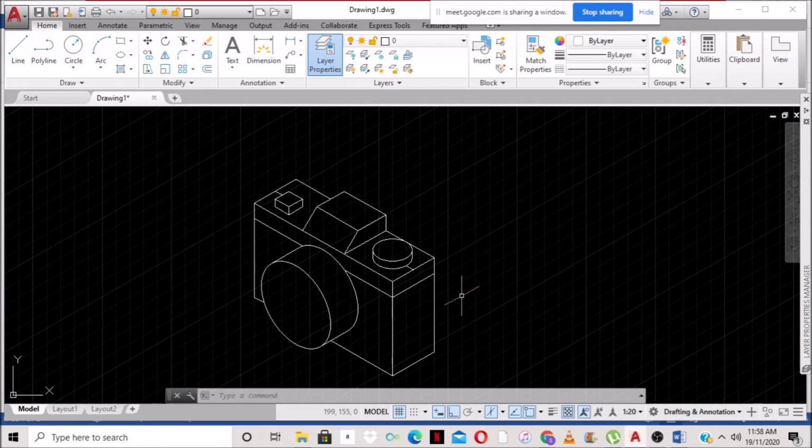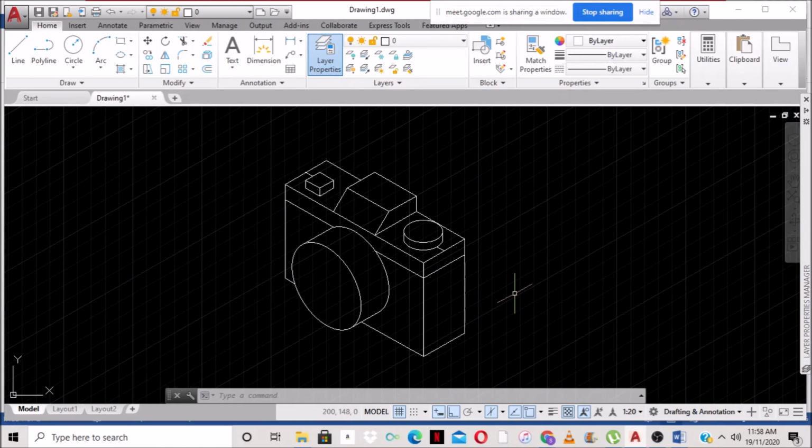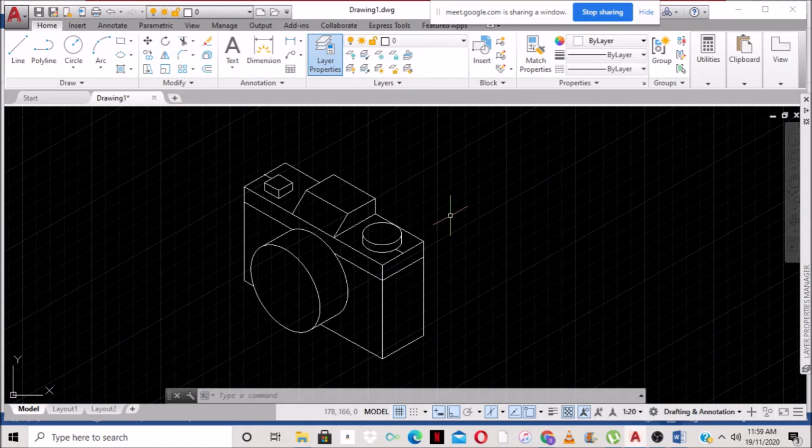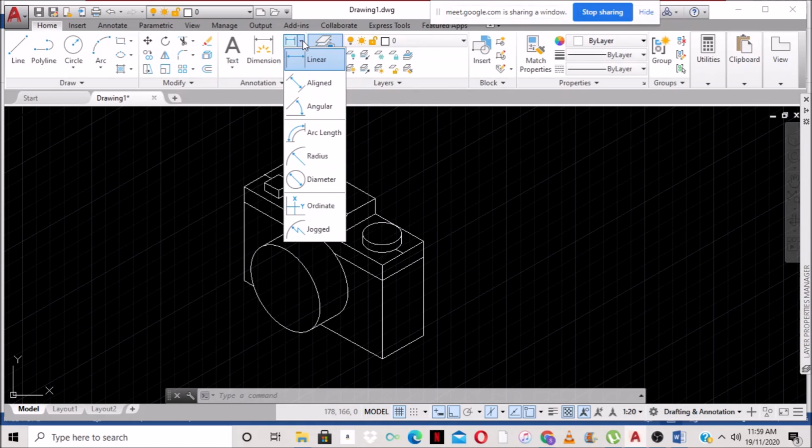So now we can go ahead and dimension, so we can add our measurement, right? So what do we need to do now to add our measurement to this joint? Dim edit. Dim edit, good. Or we can just come here in annotation, right? And we can select here on linear and we select aligned. Follow?